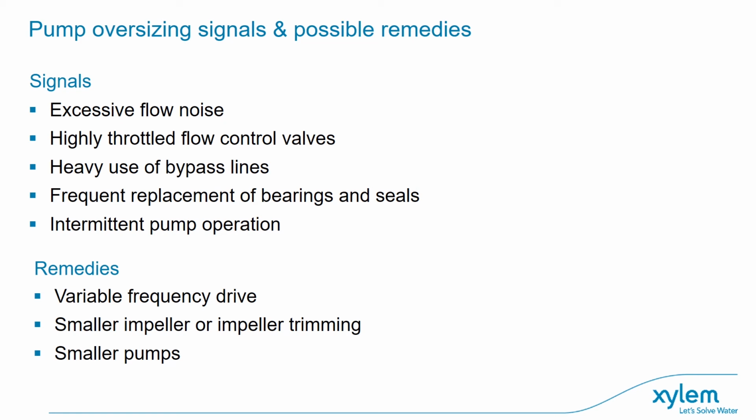Actually, we know that cavitation sounds like stones inside the water. It has the same noise effect. Highly throttled control valves mean that you continuously change the back pressure to which the pump is exposed and for which it has been designed. So a restrictive position of the valves, on top of the wear, can cause issues because pumps run very far from the best efficiency point at which they have been selected.